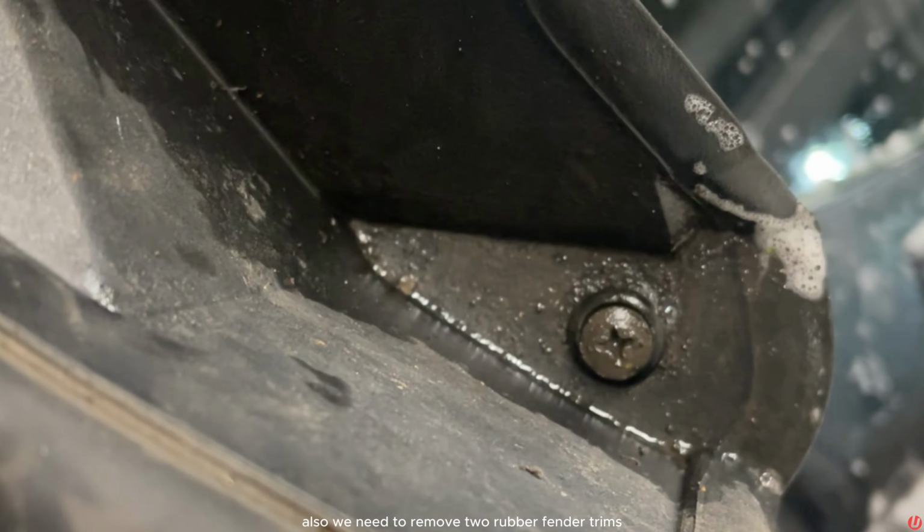Next, we will use a plastic trim removal tool to run under the cowl panel and on top of the windshield, from the driver's side to the passenger side. This action will disconnect the cowl panel from the cowl dash panel. To remove the cowl panel, we must grab the cowl panel, lift it up, and pull it toward the front of the vehicle. We have two options here.